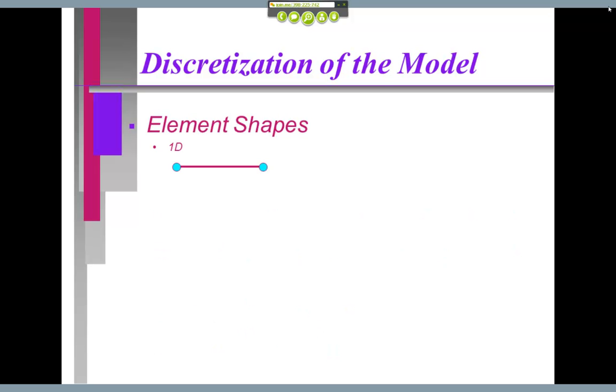If we wanted to look at the 1D nodes, they are locations along, say, the x-axis. They are used whenever doing rod type elements. So if you're just trying to approximate this cantilever beam by a simple rod where you specify the cross-section of the rod, you can represent it just by x values representing the nodes. An x value of 0, an x value of 1, an x value of 2, an x value of 3. You could break it up into a rod that had a number of nodes along it.